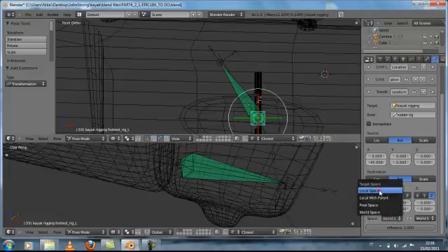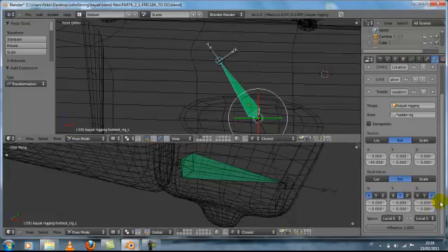Remember to select the local space, okay, and the z-axis. So we select this one, while here is the axis that refers to the source bone, and we know the source bone rotates along the x-axis. So select X, and the angle is 0.35. Let's say 35. Okay. So when I rotate,